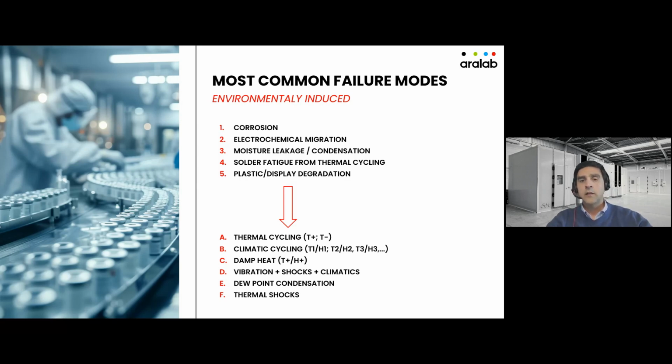Okay, a very common, especially in electronics, is solder fatigue. Okay, so the continuous heating and cooling of the sample may lead to solder fatigue, and this is a very common cause of failure of products every day. And then finally, plastic or display degradation.